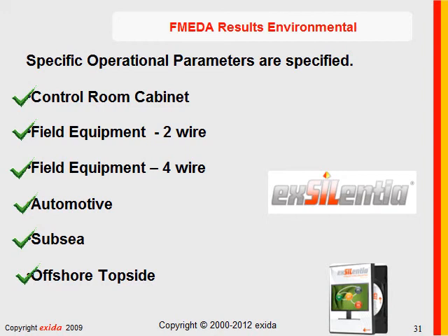Ironically, for some equipment, subsea environment, which sounds pretty bad to me, produces a lower failure rate because the temperature is so much lower. You can imagine any component where the failure rate goes up with temperature will have a lower failure rate with lower temperature.